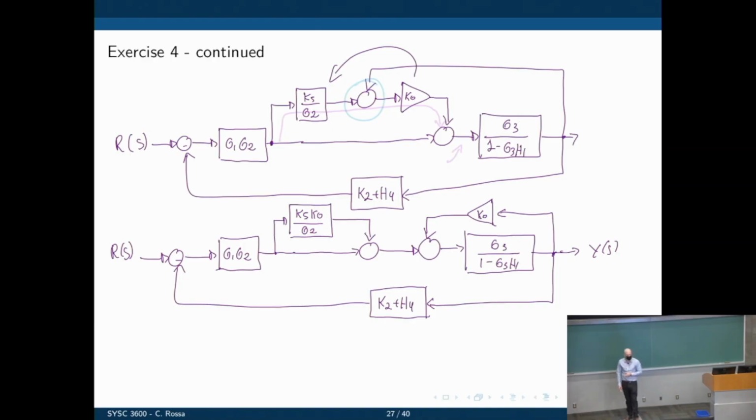Okay. Now our job is easy. So that is really the tricky manipulation in this diagram. What do we do next? Right, yes, we can eliminate the feedback loop from K6 and G3, 1 over that. What else can we do? We can deal with this guy here. That is what is happening there. They are feeding the same point. They're picking off the same signal. How do we simplify that?